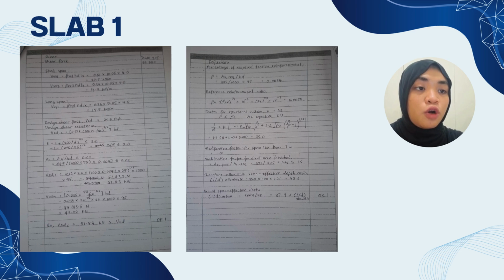These loads are then combined to obtain the total load and further factored to obtain the ultimate design load using the appropriate load factor. Once the ultimate load is known, the bending moment for the slab is calculated. For a one-way slab, the bending moment is typically determined using the formula, assuming simple support conditions. For a two-way slab, moment coefficients are used to calculate bending moment in both directions based on standard design tables that consider the slab support condition.